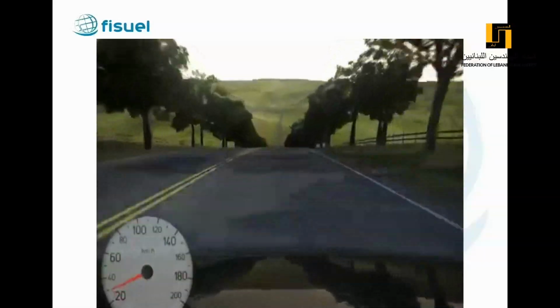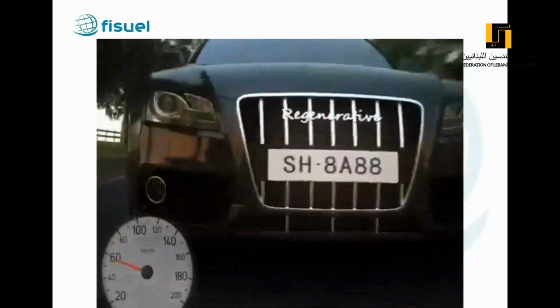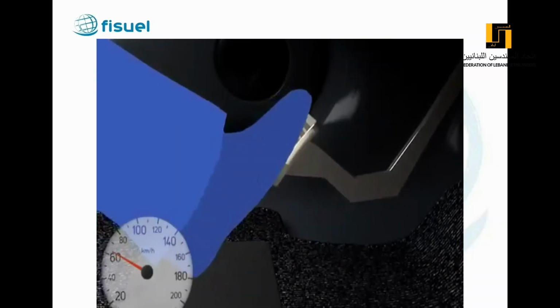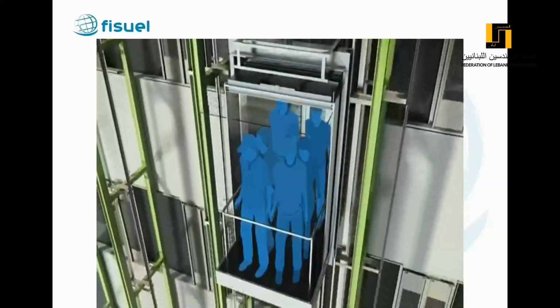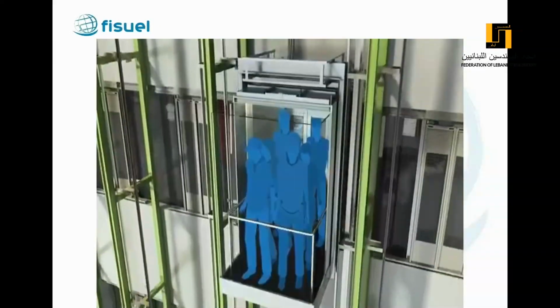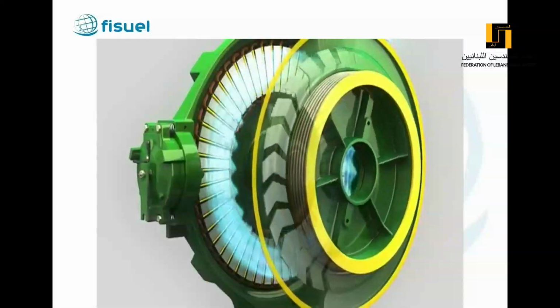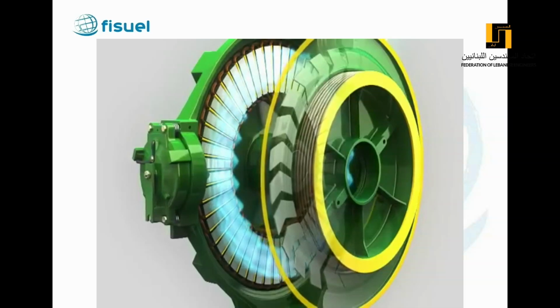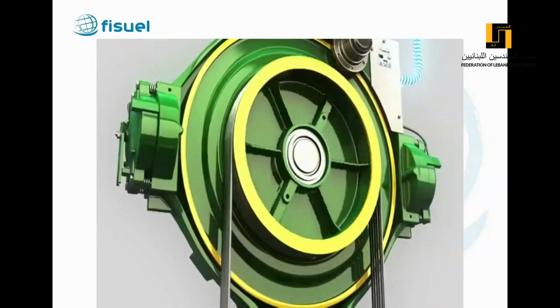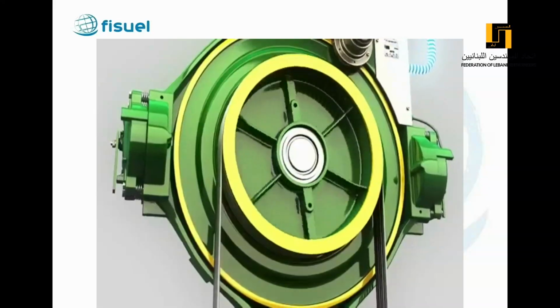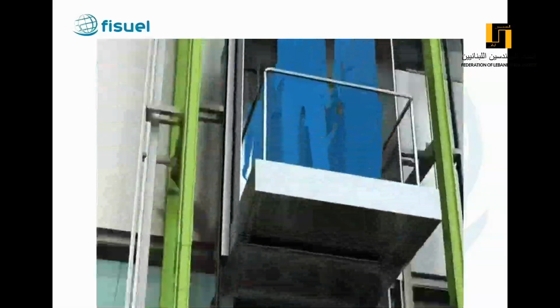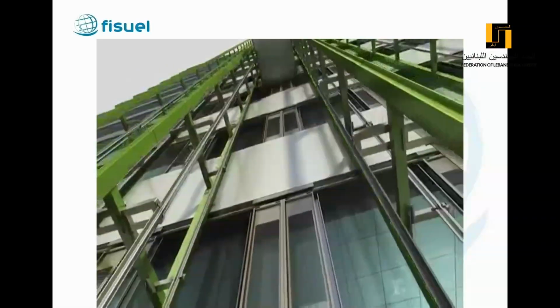It's just like a car driving downhill. When it reaches the required downhill velocity, the brakes are applied continuously to keep the speed constant. With the electromagnetic braking, as the car approaches the destination floor, the elevator decelerates and the motor continues to generate energy. This energy can then be reused elsewhere in the building. The greater the operation speed and distance traveled, the larger the weight variation between car and counterweight. Or the more frequently the elevator is used, the more energy is regenerated.